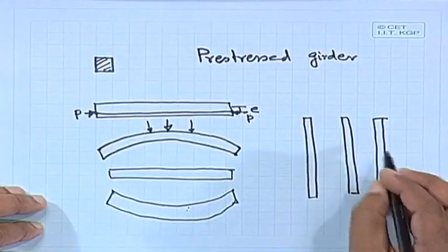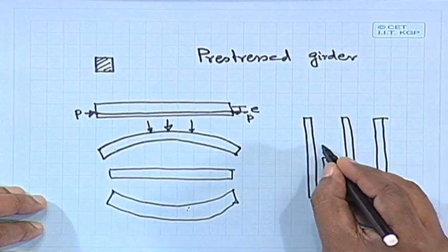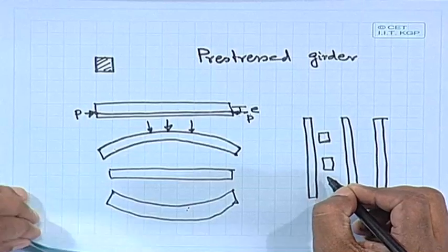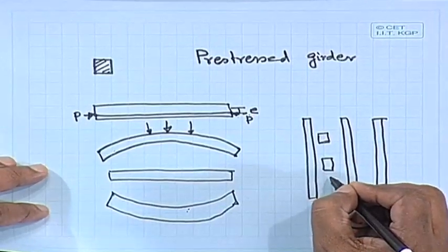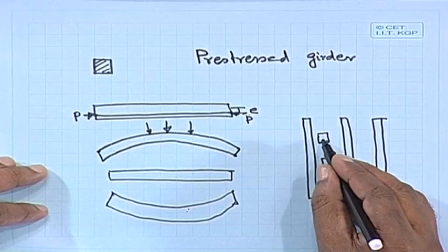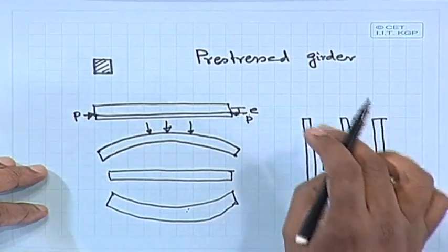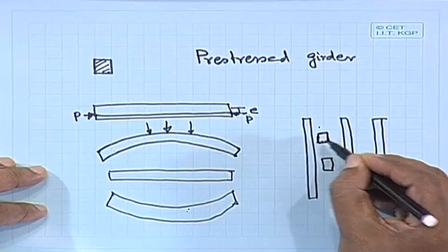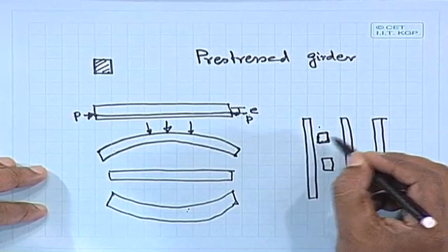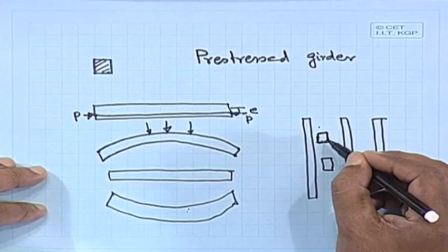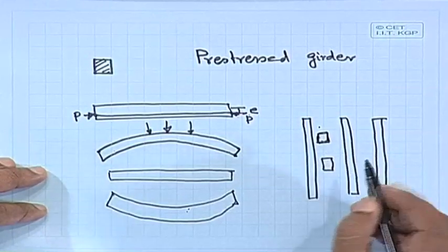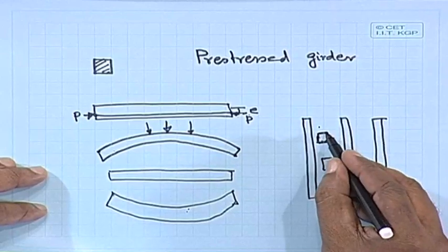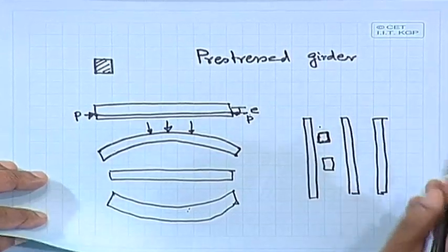Now here we are having the wheel load. This wheel load is coming as a concentrated load. So now if we have the concentrated load here, how shall we take the effective width of the loading? This loading, the impression directly, we do not take it, we take a little more. So how much more we can take, that we have to find out. In this case, there is always one wearing coat.